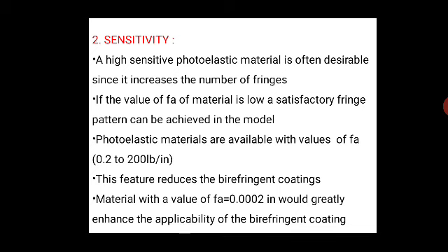If the sensitivity value for a model material is low, satisfactory fringe patterns can be achieved in the model with relatively low loads, and this feature reduces the complexity of the loading.